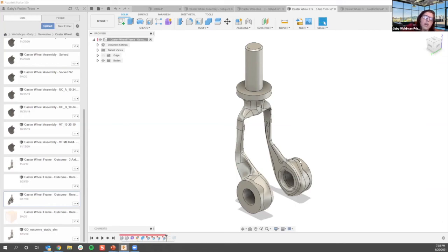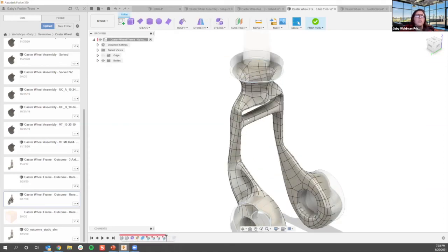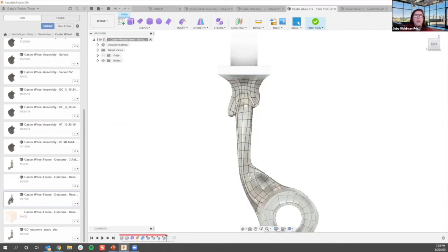So this outcome is a T-spline body, right? What we normally create when we create cylinders and rectangular prisms in CAD are called BREPs, boundary representations. And this is a different type of solid called T-splines. It's this purple button here, called form, in the form workspace. If we right click on the timeline and click edit form, it's going to take us to the edit form workspace, and we can edit these elements in an organic fashion.